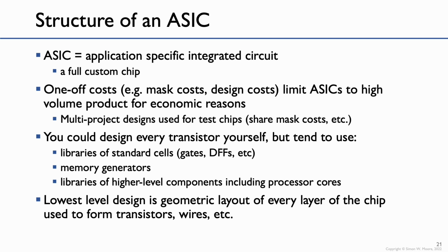Actually, in order to do test chips, there are various services that do multi-project designs. This is where a mask for a large chip will contain several smaller designs, and this is useful for running test runs, so as to amortize mask costs.